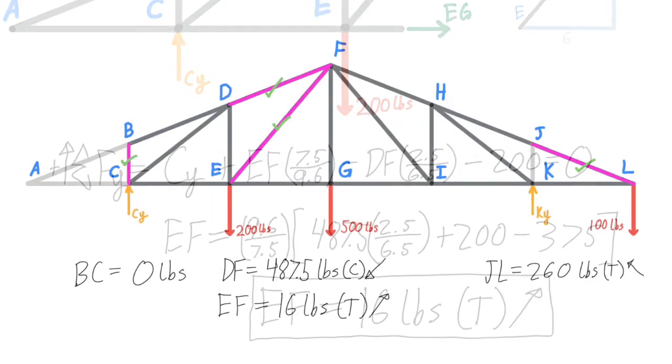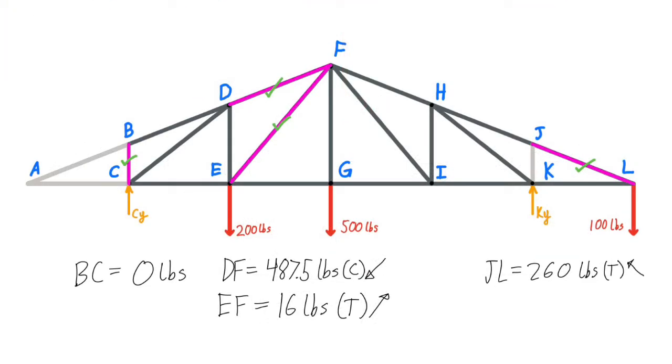In this problem, we learned how to work with the special properties of a truss, knowing that it is made up entirely of two-force members, as well as how to identify any zero-force members. For solving the internal forces of several members, we used the method of joints and the method of sections to understand how each member of the truss is experiencing a tension or compression due to the external load on the structure.